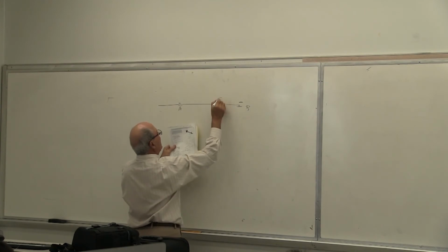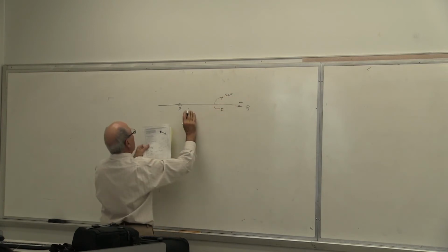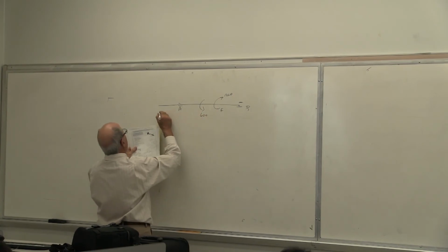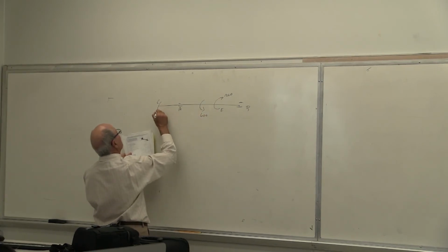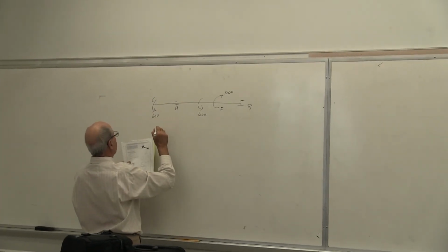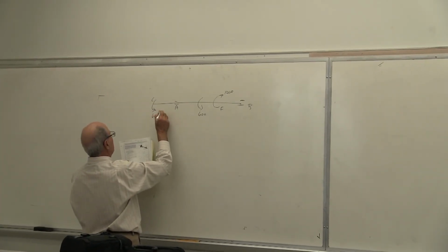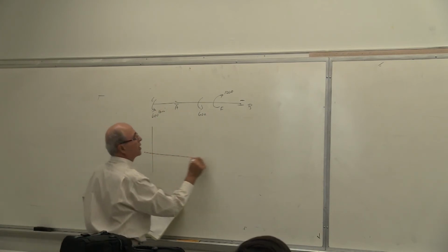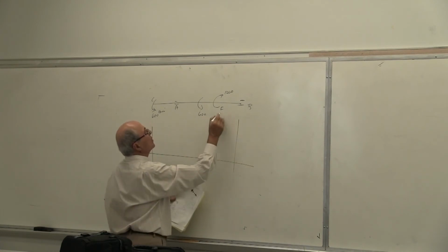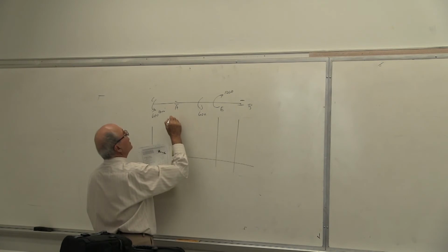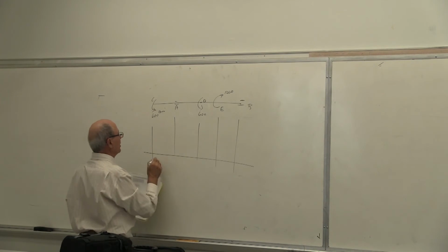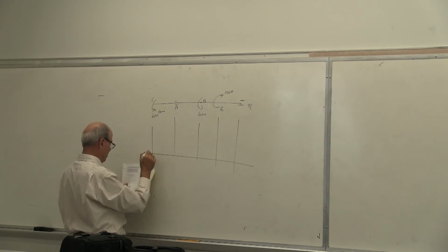Then you have here at E a torque of 1200 going that way. At D here, you have a torque of 600. And at C here, you have a torque of 600. The unit is pound inch. Is that correct or not? Yes? So your torque diagram, going along these spaces, this is point E, this is A, B, C, D, E. So you bring those points down. You start from either plus 1200 or 600, that's up to you.